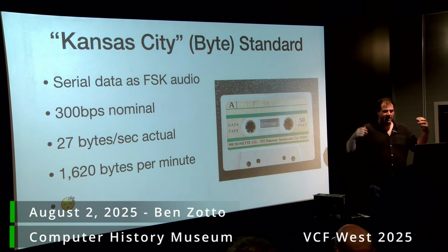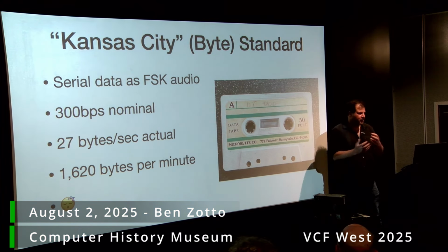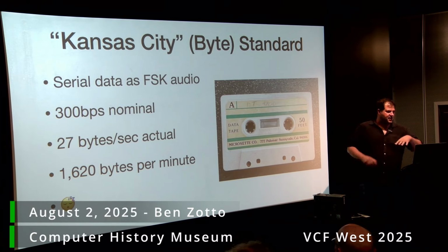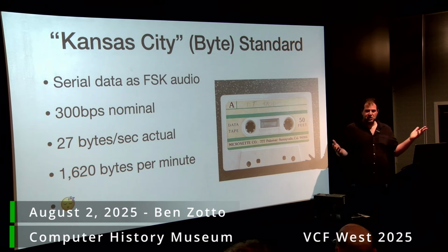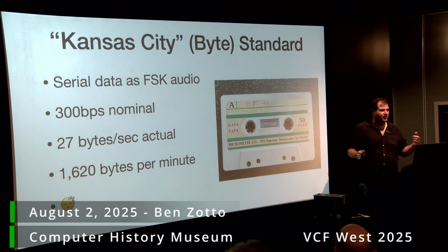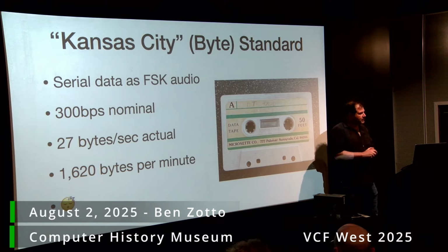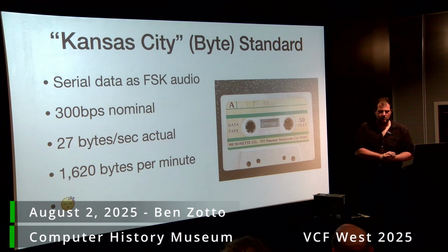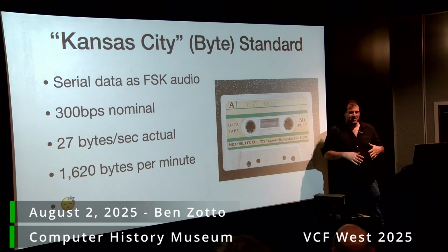It was devised by a summit meeting of people who got together in Missouri in the early winter of 1975. It stores data as serial frequency shift keyed audio, and it's quite slow. It runs at 300 bits per second nominally, which works out in practice to 27 bytes per second. That's pretty slow. It gives you 1,600 bytes a minute, and it takes a really long time to load anything substantial. So if you want to load BASIC, you push play, you go get some coffee, you come back, and maybe it's done, maybe there's an error.